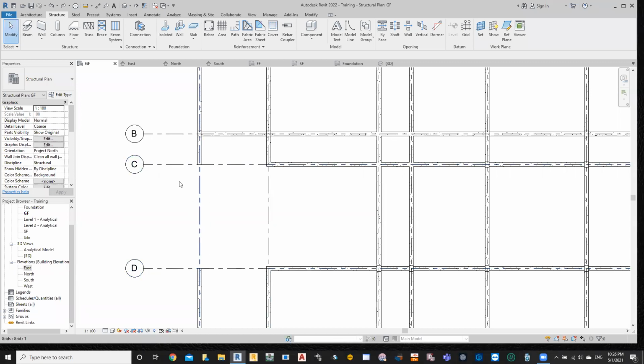Okay. This area I have deleted. Now everything should be connected. Means there is a beam here, but there shouldn't be a beam and a wall in the same place. You cannot keep a beam and a wall at the same place, because when I say a wall, it is going to be a concrete wall. It's a full RCC wall, whatever we call as a core wall.